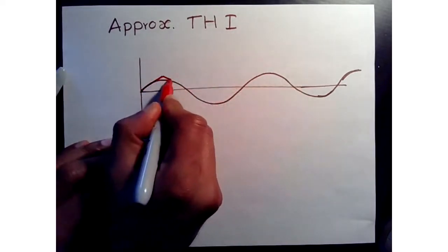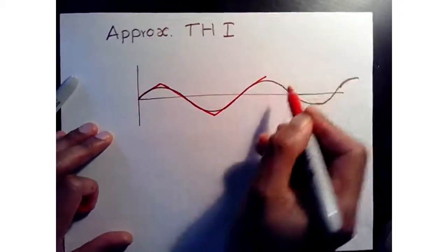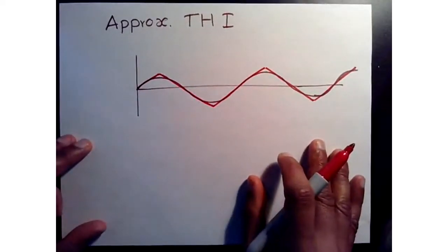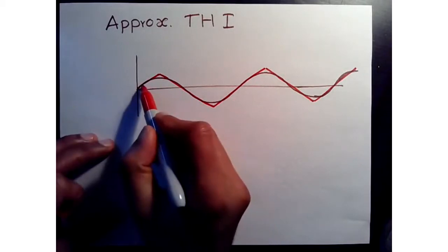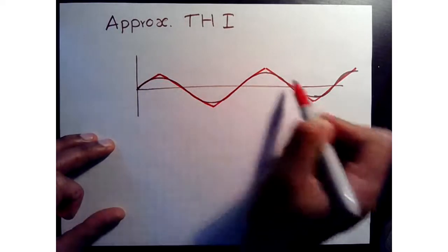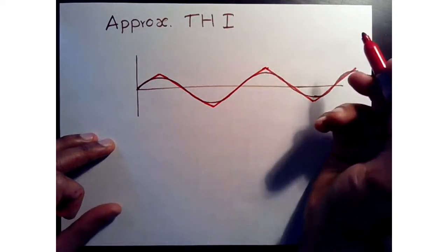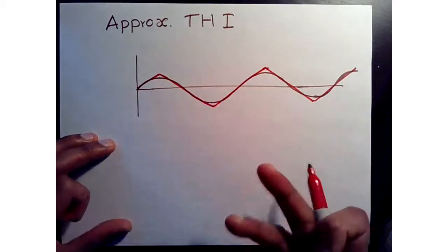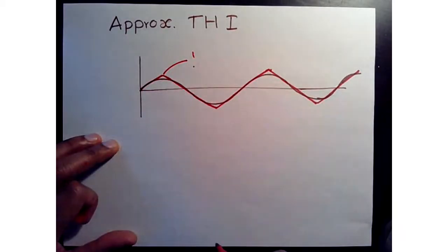We're going to use a triangular wave here. Okay, so by doing that approximation, you can achieve very similar results as third harmonic injection, and you're sacrificing a little bit more harmonic content because a triangular wave is not a pure sine wave, so you are going to see a little bit more harmonic content in your currents, in your voltages, but they're not as significant as the cost saving you get by approximating to this triangular waveform.